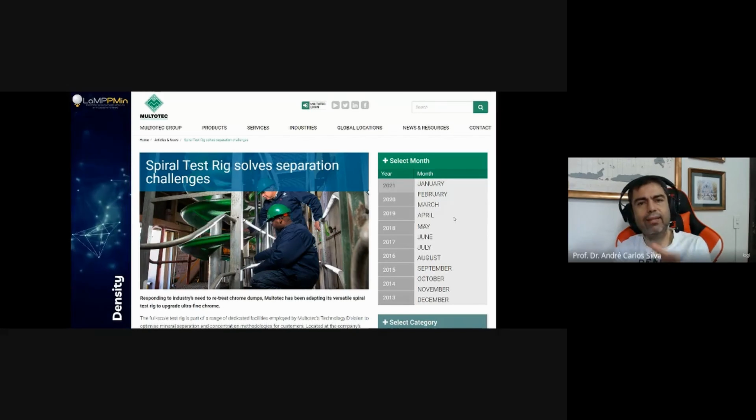So we can use better water for flotation, but we cannot use recycled or used, processed water too many times in flotation. Here, we don't have this limitation. You can virtually use the same water forever. You just have to recover it and use it again, and recover it and use it again, okay?